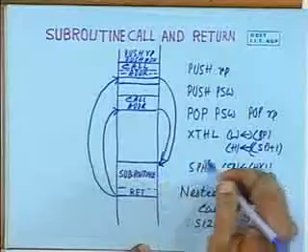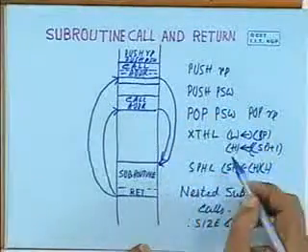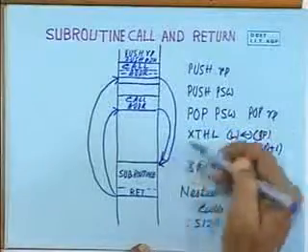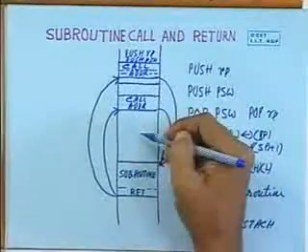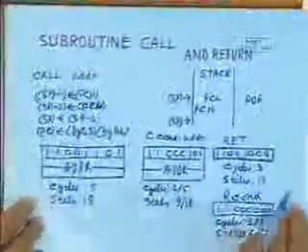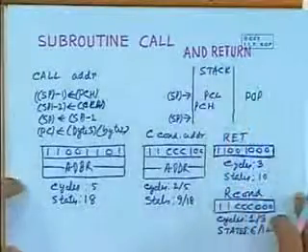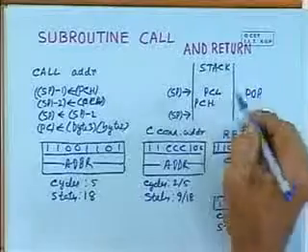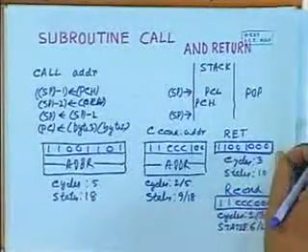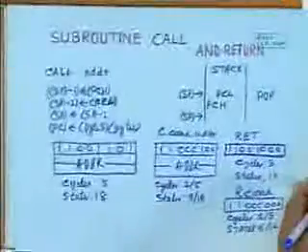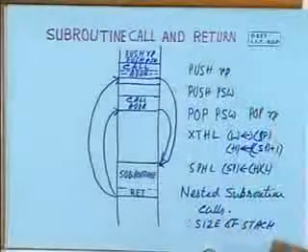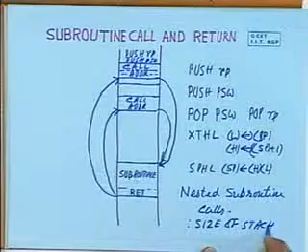because whenever you perform a subroutine call, the program counter value is stored in the stack. Each time you perform a call in the nested form, it will be stored gradually in the stack one after the other. So the stack will keep on holding values for each call, and if the stack is limited in size, then at some point there will be stack overflow. So you have to keep track of that so that stack overflow does not occur, or you have enough size of stack so that nested subroutine calls can be performed to as many as possible.